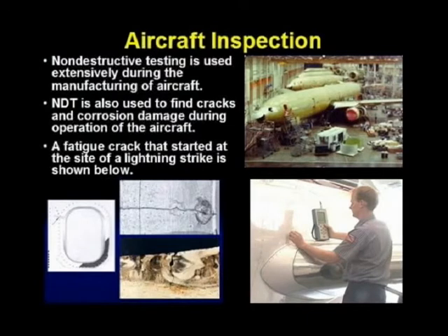I have worked in this industry and was involved in finding 10,000 soft rivets on the first DC-10, acoustic emission monitoring a 1 million pound proof test of the horizontal stabilizer strut on the DC-10, and have even performed eddy current crack detection on the wheels of the Cummins corporate jet. Did you know that some military cargo planes are mounted with acoustic emission sensors, which tell the pilot when the aircraft is good for only one more landing?